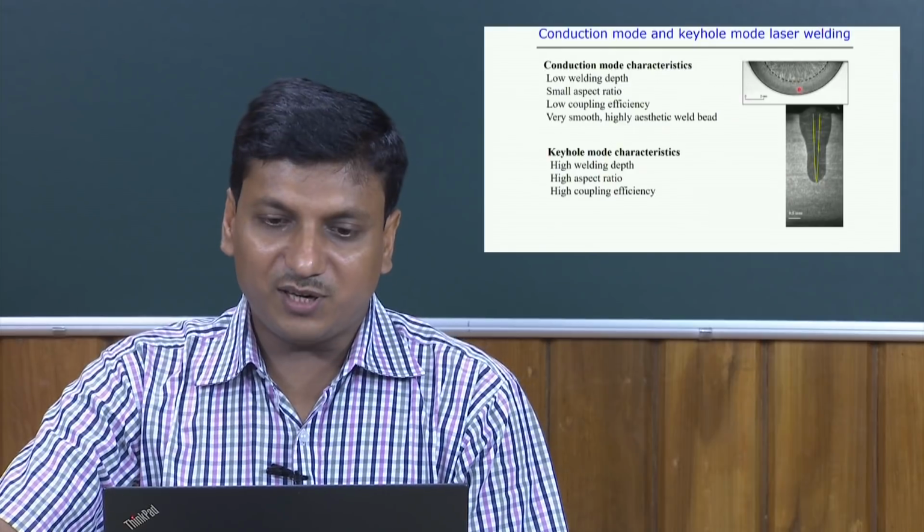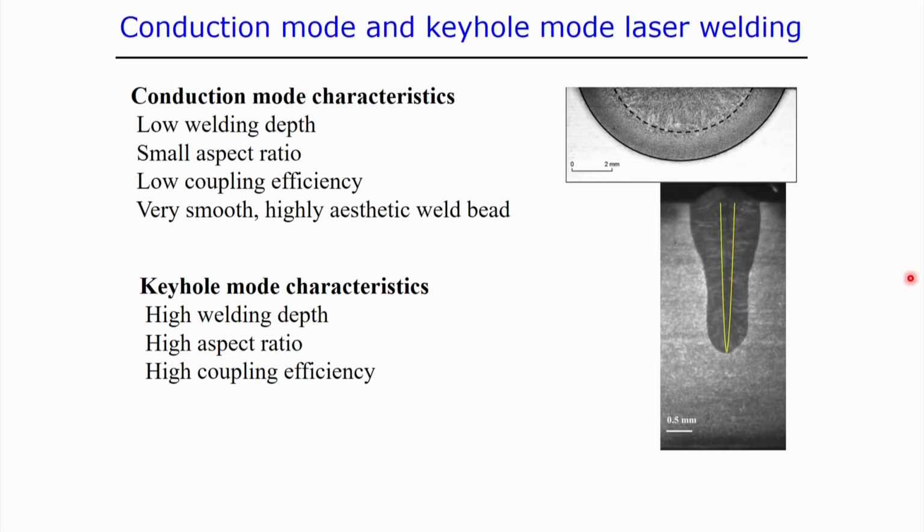Here, if you see, this weld pool has been measured after post weld treatment, that means after solidifying the molten zone, we take the macrograph and estimate the size of the weld pool. We can visualize the size of the weld pool during the welding, but the size of the weld pool does not indicate the size of the keyhole. The keyhole was probably marked by the yellow color. The keyhole size means the vapor domain during the welding process, and the remaining part is the molten zone.